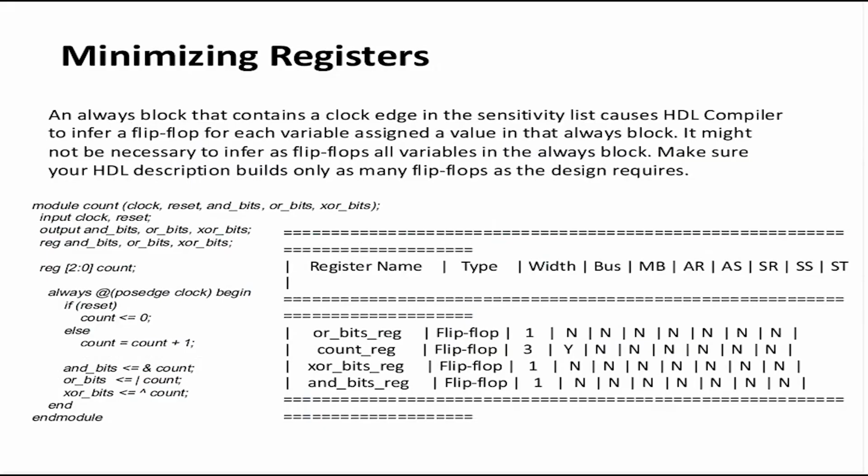Now let's see how effective coding gets rid of unwanted registers. Sequential elements are not easily optimized away. It's not like combinational logic. Sequential elements represent timing sequence, and in most cases, when Design Compiler sees a sequential element in your always block in your RTL code, it will map it to flip-flops, and it doesn't know if they should be optimized away or not, right?